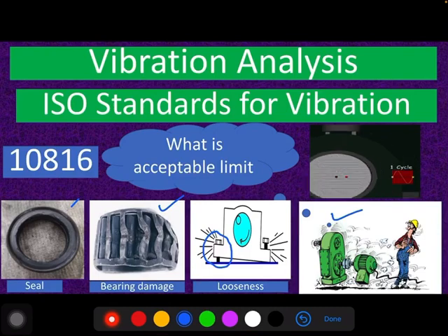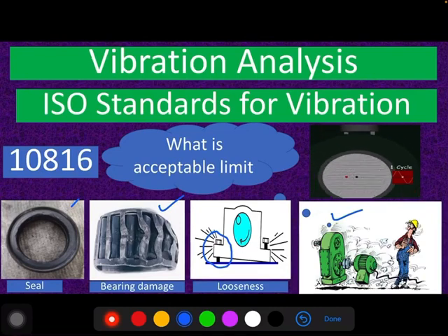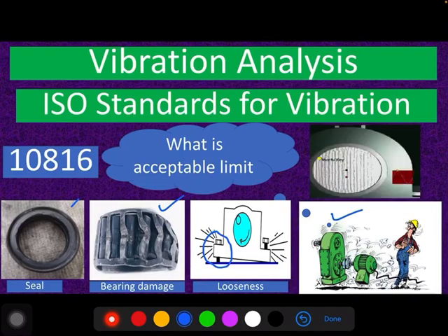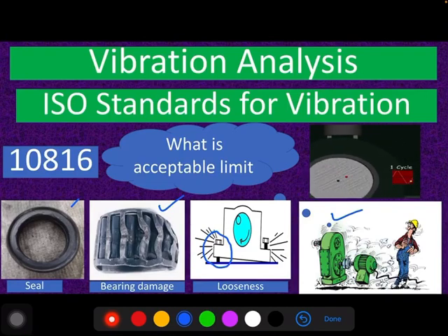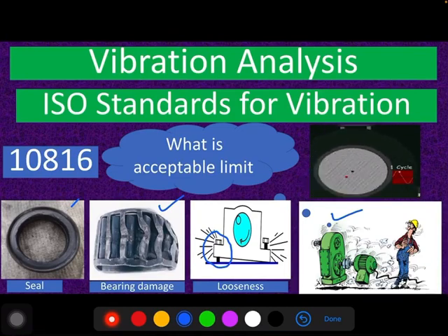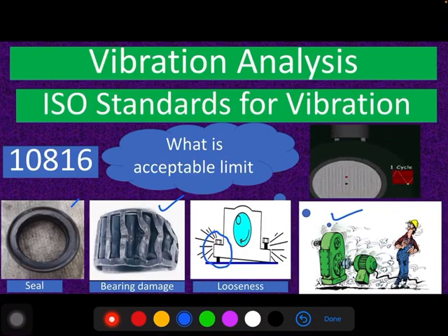So vibration is nothing but a response of a system. Means any change in machine behavior directly reflects in vibration. So we need to measure the vibration amplitude in the vibration monitoring methodology. It should be the topmost priority for any mechanical or electrical engineer to understand the machine behavior. So to keep the machine healthy, you need to set the vibration alarm, and the machine should run with the least vibration level. I will cover that in the next slides.